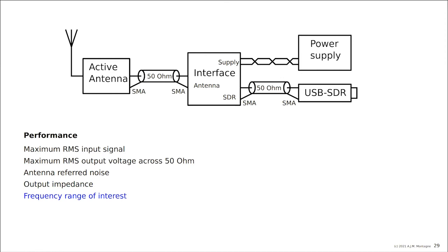The frequency range of interest, something like 10 kilohertz to 30 megahertz, if I remember well. The response type, and here I think this wasn't really specified, but we assumed a maximally flat magnitude frequency response. IMD, I remember minus 50 dB IM components, in-band IM components.